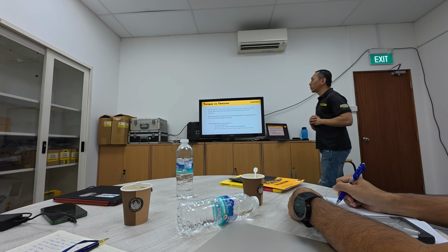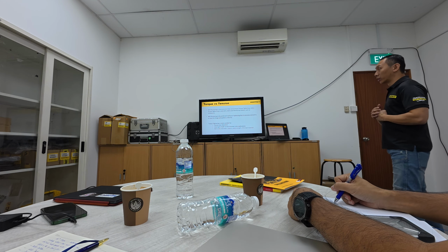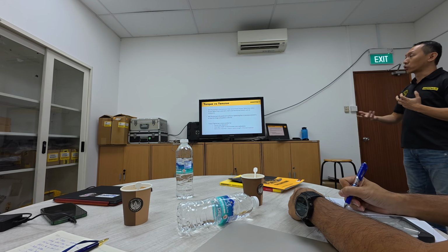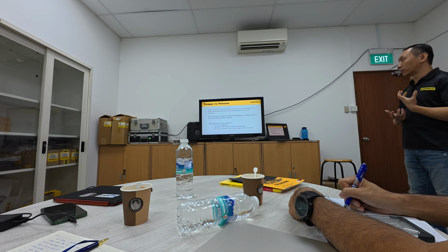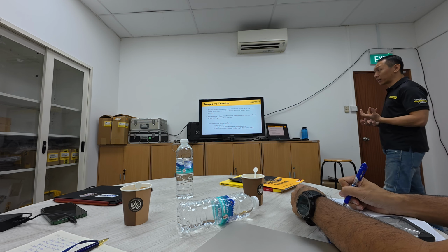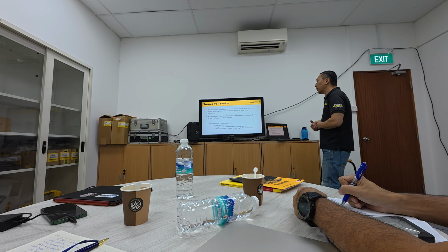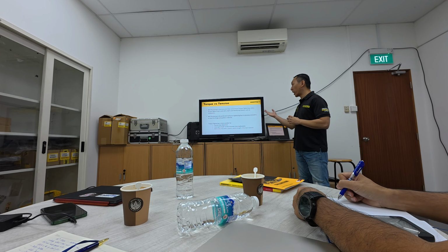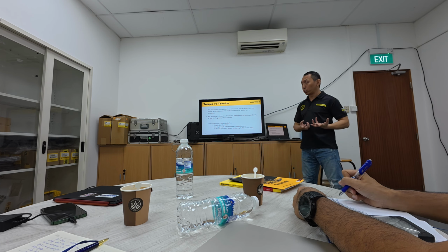Bolt tensioning is more accurate than conventional torque tightening, unless the torque tightening is used with a load monitoring system like ultrasonic. Tensioning is the preferred method of tightening due to accuracy and the ability to load the flange and gasket uniformly. But like I said, it's very dependent on the tool fit.